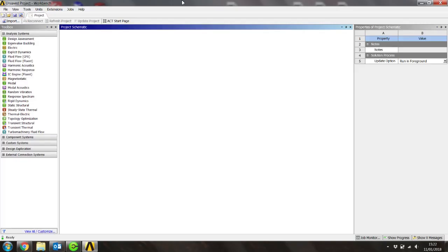So the first thing you're going to want to do is to open ANSYS. If you're doing that on the Engineering PC Labs, go to the Swansea Unified Desktop icon, click on Specialist Apps, College of Engineering, ANSYS, and you should find ANSYS Workbench in that folder. When you open that, you'll be presented with a screen which looks like the one in front of you right now. We'll refer to this as the main ANSYS home screen or the project schematic screen.